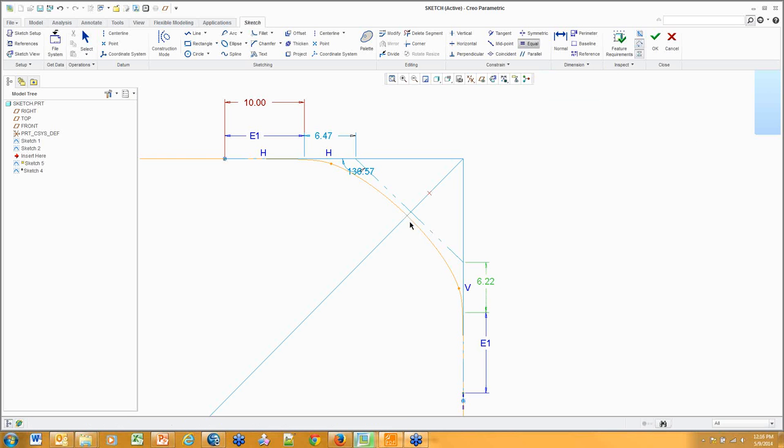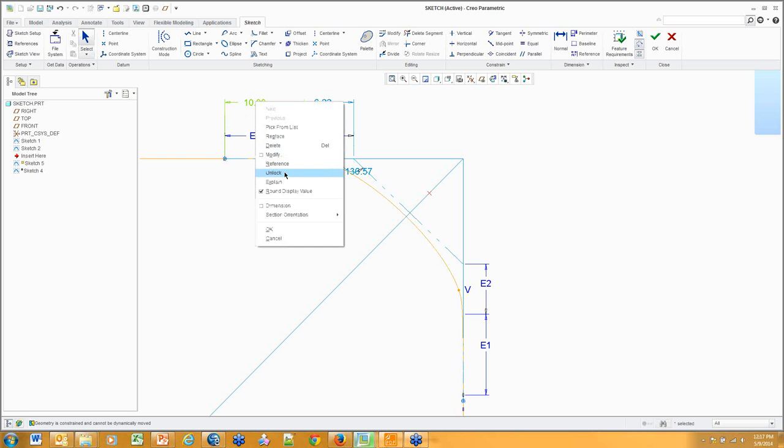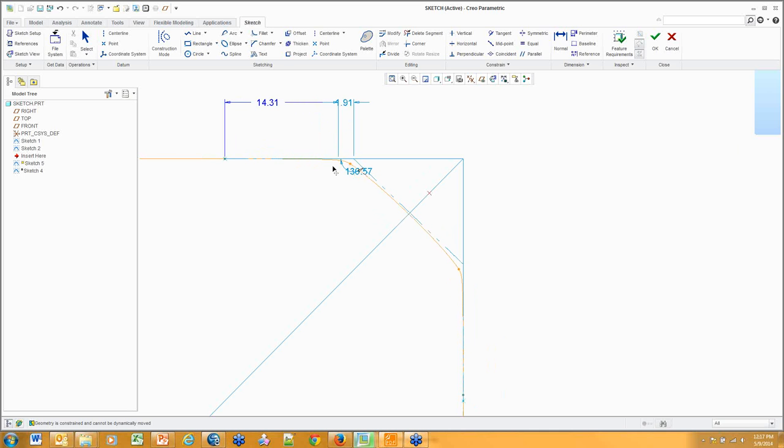So next we'll go equal this value and this value. Okay, we'll make that, make this 10 maybe. I'm just going to get rid of this thing real quick here. All right. Now, if I want to come in here and actually drag one of these values, I'm not able to. Notice I'm trying to click on that little vertex. It's not working. The reason is because this value is locked. Just make sure that if you do have that configuration setting set, that you unlock it.